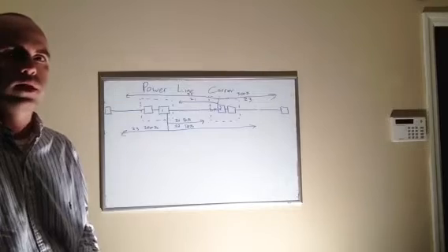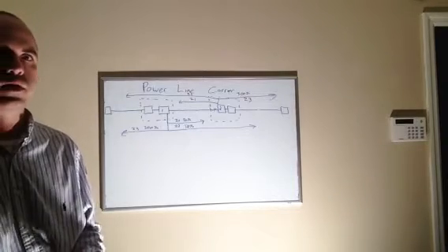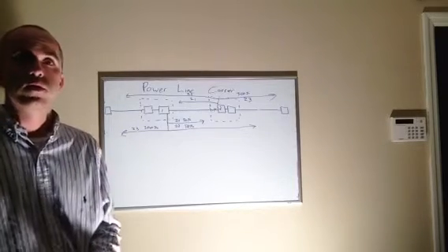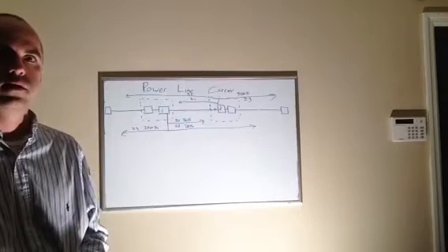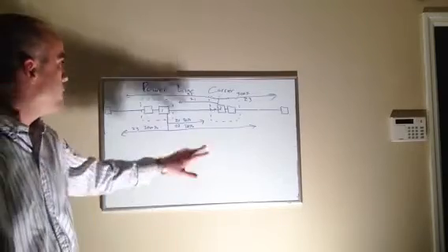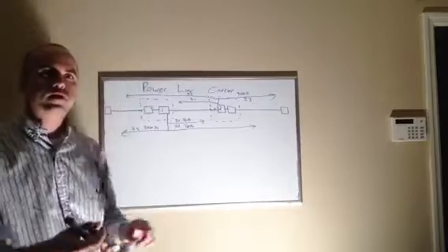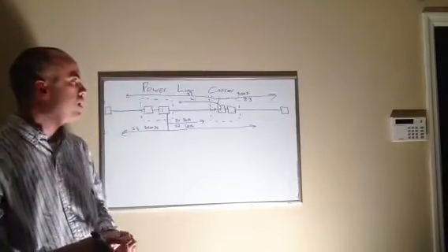All you system operators out there need to remember that. If you're in exams or interviewing for a job or sitting on the desk trying to troubleshoot a fault, pilot protection gives us high speed tripping on 100% of the line.